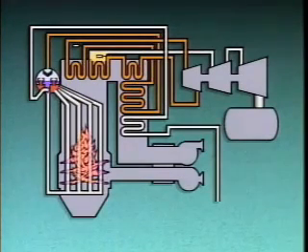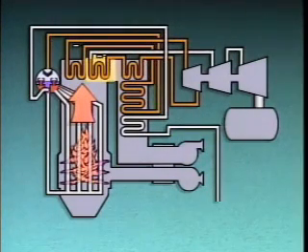The attemperator sprays water into the steam flow if the steam gets too hot. The secondary reheater in this example can also be classified as a radiant reheater because it's located in a line of sight with the boiler flames and receives most of its heat by radiation from the flames.